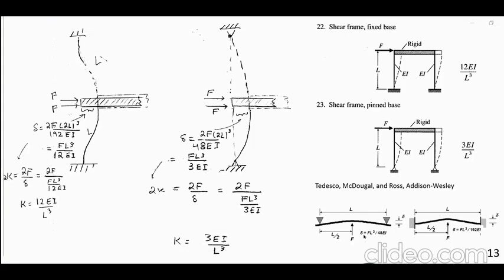You know what the deflection is? It is FL cubed over 48 EI, except that there are two F's acting, and there is a length of 2L. And that's how you're going to get it. Okay. So, let me first... Okay, let's move on.